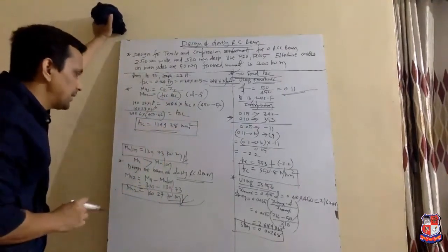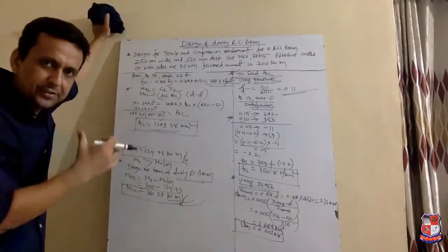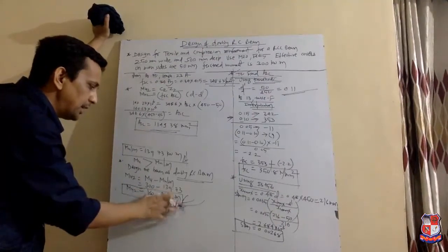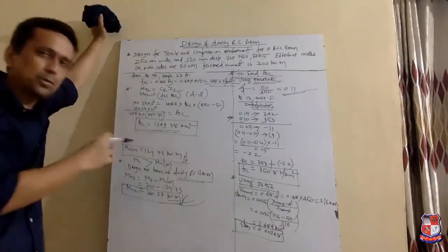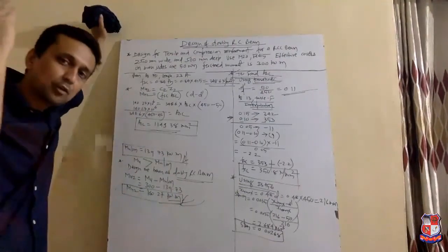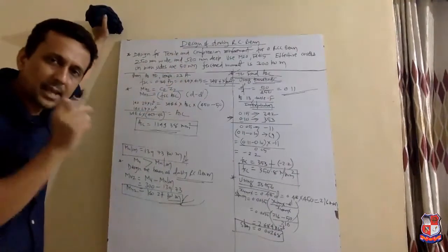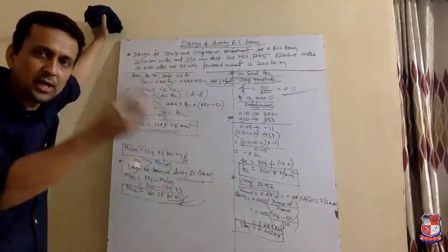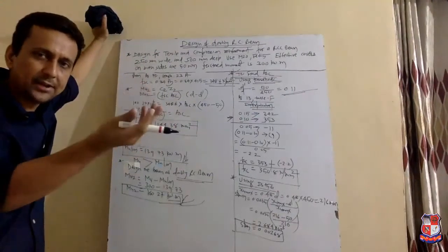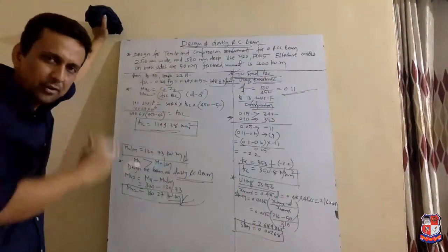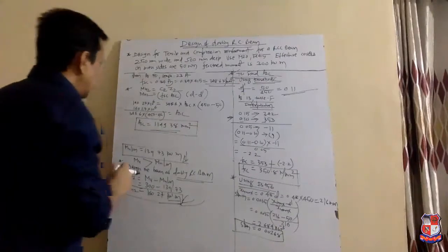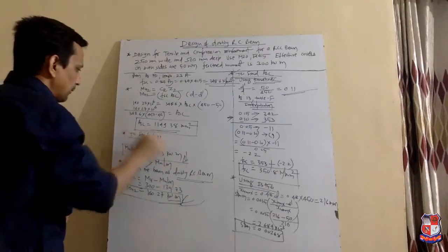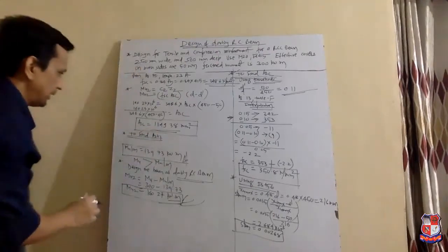So, what does this 1149.38 mm square mean? It means to resist this extra 160.27 kilonewton into meter, we have to provide the reinforcement in compression zone having minimum area 1149.38 mm square. So we have already provided the reinforcement required in compression zone for that auxiliary section. Now our target is to find AST1, right? So what is AST1?